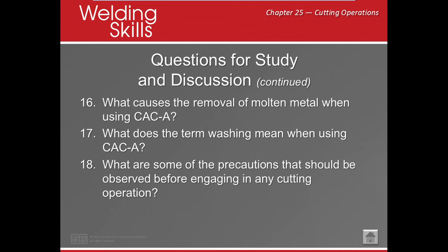Well, we also want to think about welding operations as well. If you guys are doing this in your garage, you need to remember those little sparks that fall on the ground, those little BBs or whatever, they can go up to 25 feet. So that means you need to pay attention if you have a water heater, some boxes, or anything like that, because they can smolder up to a half hour after you're done. But we also want to make sure that there's nothing around our cutting area. Is there something combustible, right?